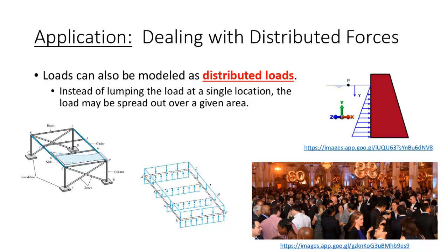but also uses vectors and forces and moment arms that I can then use to perform a static analysis. Now, as structural engineers, we have a number of loads that we model. Sometimes we'll model uniformly distributed loads, like you see here on this bottom central figure. It's like maybe 2,000 pounds per foot or 200 pounds per square foot. It's just a constant pressure or a constant magnitude across that length.